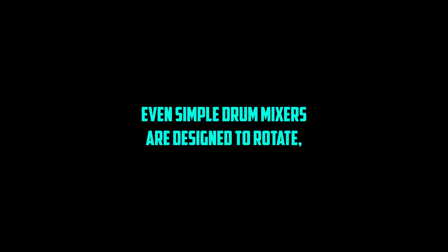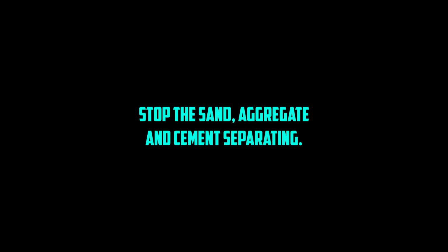Okay, foundations and basements sorted. Moving up to the main structure. Concrete work above ground. Right. The handbook breaks concrete work down into mixing, transporting, and placing. Even simple drum mixers are designed to rotate to stop the sand, aggregate, and cement separating, that's called segregation, ruins the mix.